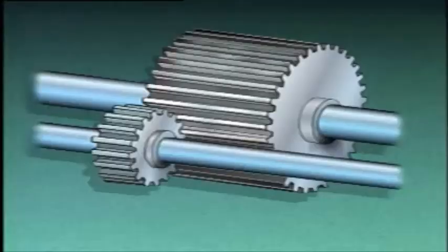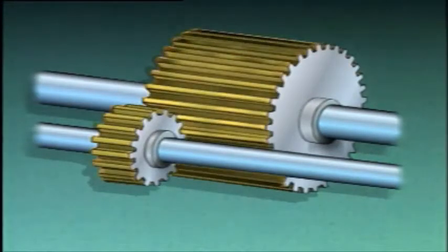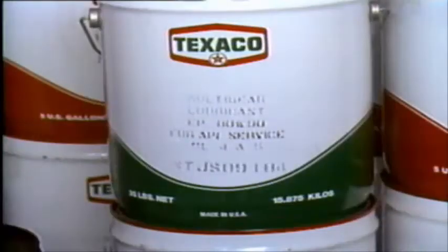Gear oils usually contain chemicals called EP additives to protect metal surfaces against wear from rubbing. EP additives are used in greases or oils to form a protective coating on the exposed metal. The coating stays in place and prevents metal-to-metal contact, even if the lubricant is rubbed away. Lubricant containers usually have EP on the label if they contain an extreme pressure additive.